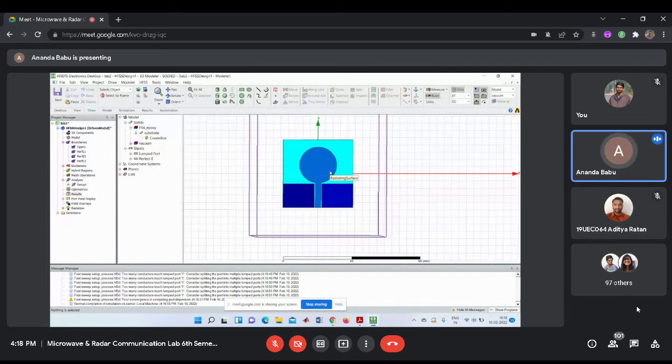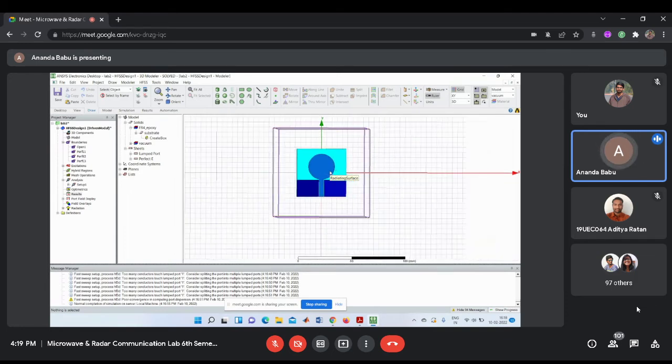In the antenna simulation, we are giving the input source only, and you do not check the output. So how can you check whether your antenna design is correct or not? You are giving an input, S11, the excitation, and checking how much reflection comes back. If the input is not getting back, the reflection is very low. That means your input is excited and electromagnetic waves will travel into the free space.